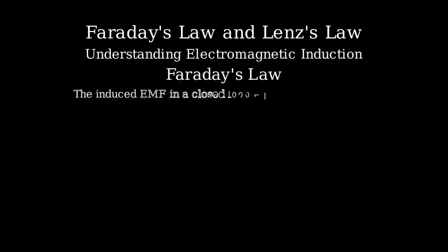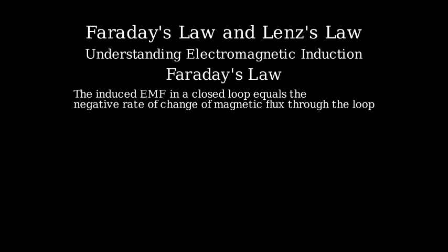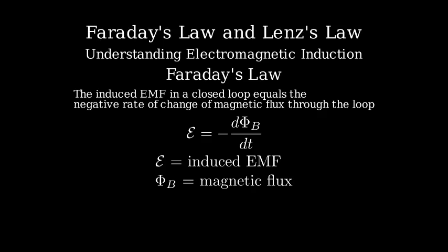Faraday's law states that the induced electromotive force, or EMF, in a closed loop is equal to the negative rate of change of magnetic flux through the loop. This can be expressed mathematically as EMF equals negative d phi b over dt, where EMF is the induced electromotive force and phi b is the magnetic flux.